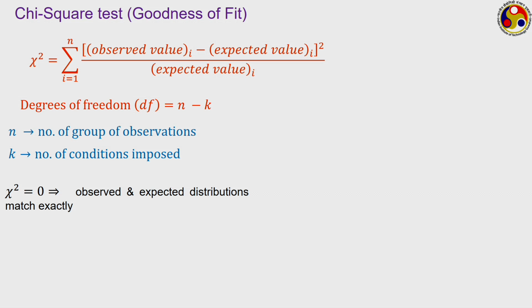The observed values come from whatever our measurement device is giving, and expected is what we want. Going back to the example of the pressure reading, our expected value is 400 kilopascal for all of them, but observed we are getting something else. So, over this set of 12 data points, that is small n equal to 12, we can calculate the chi-square value.